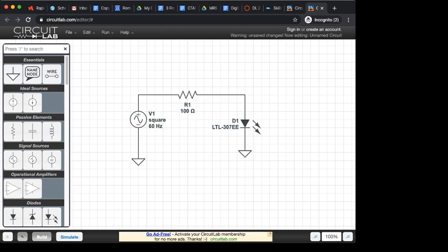Now, we're going to have a problem, as you will see in a second. If I actually built this circuit in real life, like plugging an LED through a very small 100 ohm resistor, it's probably going to burn out my LED. And so what we're going to do as part of our circuit design is try to figure out what resistance I need here to make sure the maximum voltage from my AC source doesn't exceed a parameter for this load.